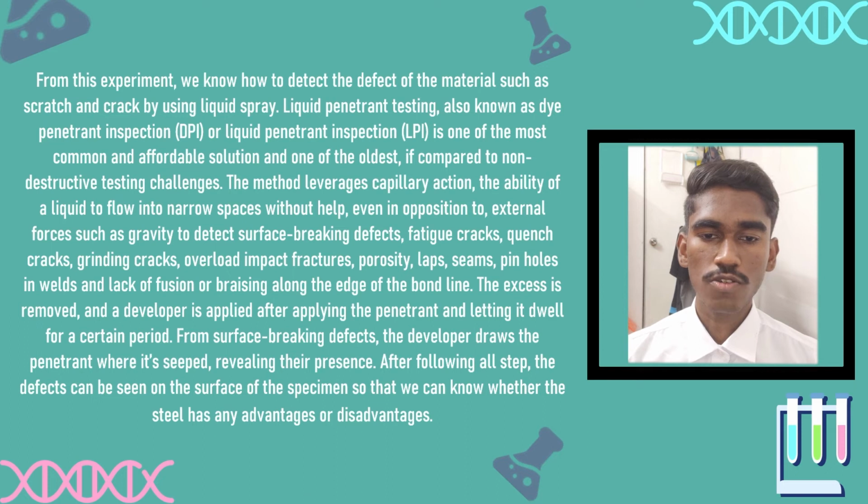Liquid penetrant testing, also known as dye penetrant inspection or liquid penetrant inspection, is one of the most common and affordable solutions, and one of the oldest, among non-destructive testing methods. The method leverages capillary action, the ability of a liquid to flow into narrow spaces without help, even in opposition to external forces such as gravity, to detect surface breaking defects, fatigue cracks, quench cracks, grinding cracks, overload impact fractures, porosity, laps, seams, pinholes in welds, and lack of fusion or brazing along the edge of the bond line.